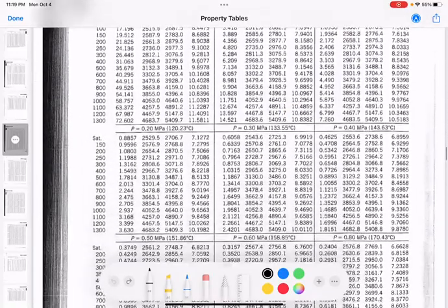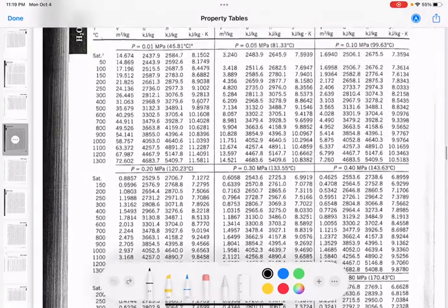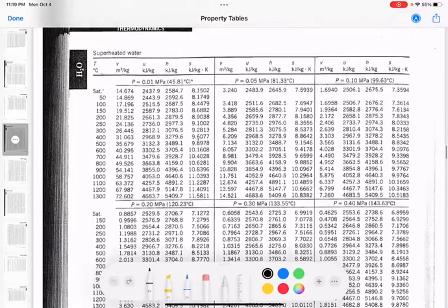And this is where we have to start doing a bit of interpolation, and it gets a little tricky in this specific case. So let's go to our superheated tables. Now, we know we're looking for a temperature of 125, so somewhere between the entries of 100 and 150. I don't know which table because this is sorted by pressure, and it's pressure that we're trying to find. But we know it's going to be somewhere between here, and we're looking in the specific volume column of each table, and we want to see something that encloses that 0.83.